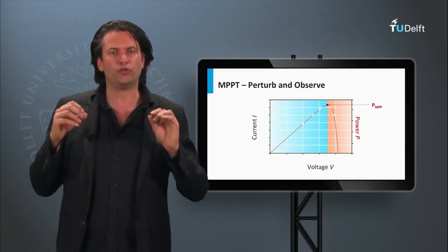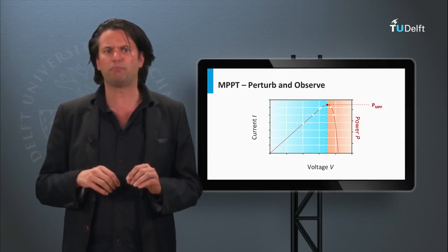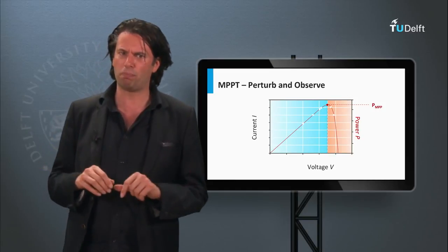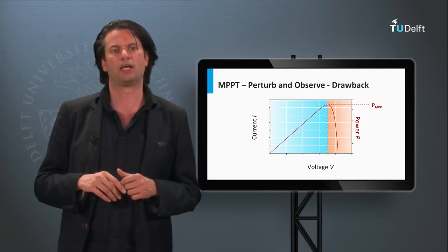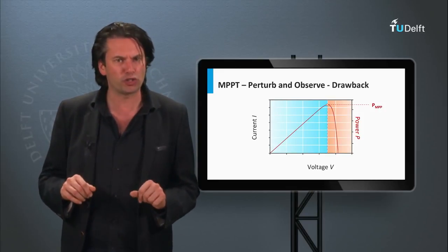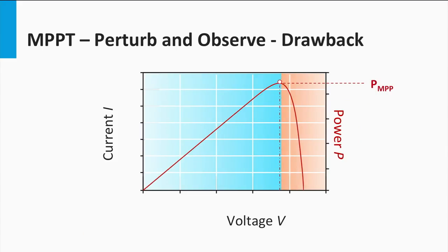It is always hovering around in the maximum power point region, although this could be minimized using very small perturbation steps around the maximum power point. This algorithm also struggles under rapidly changing illumination. For example, if the illumination and therefore irradiance changes in between two sampling instants in the process of convergence, then the algorithm essentially fails in its convergence efforts.